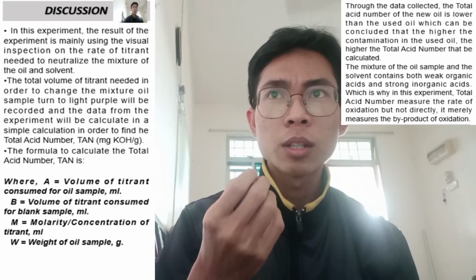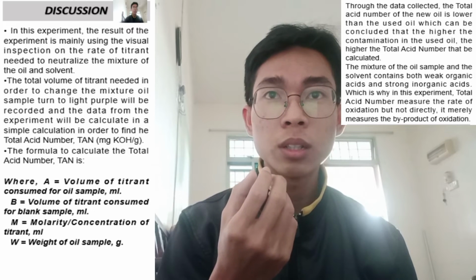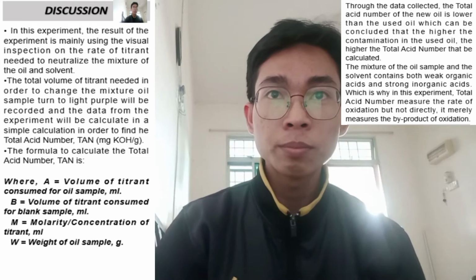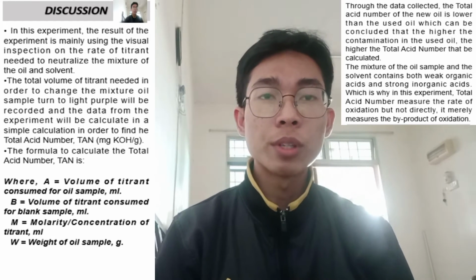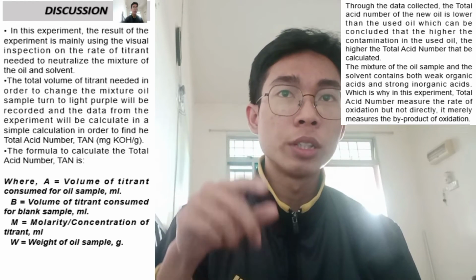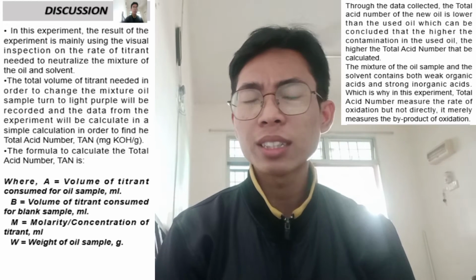We will calculate the weight of the oil sample by using the instrument. Okay, after that we will put the data into the formula and calculate the total acid number. Okay, through the data collected,